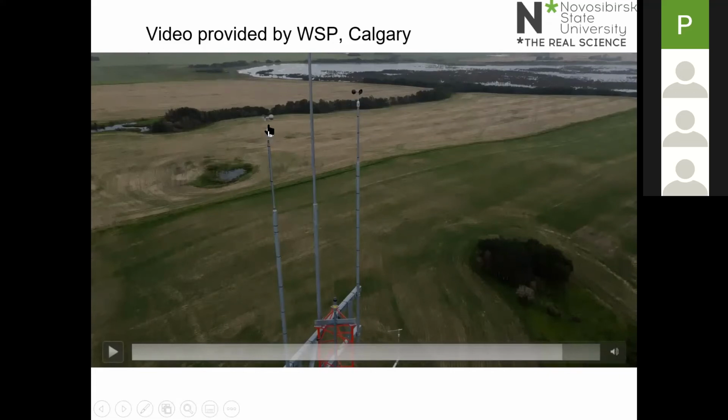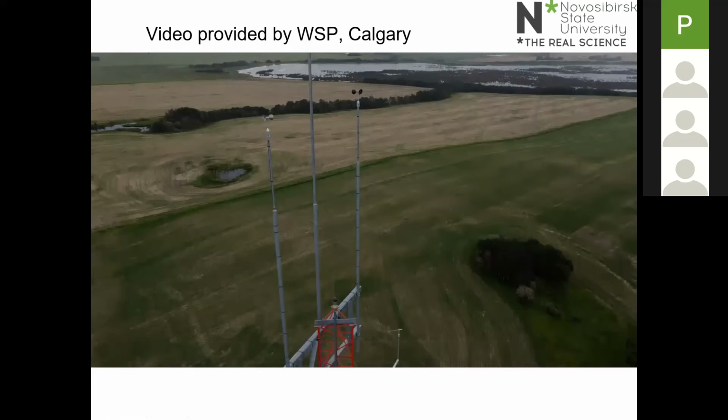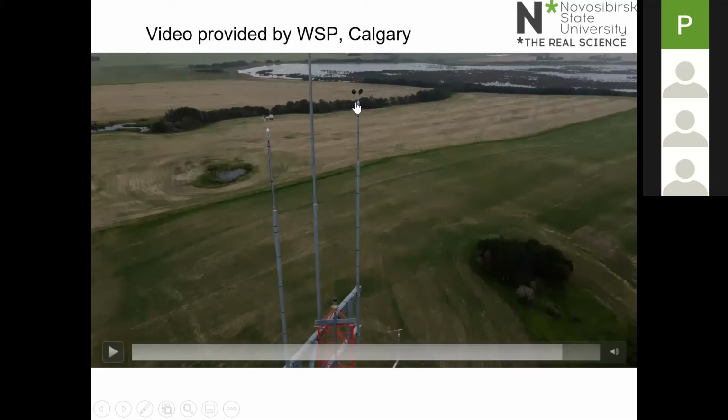And that gives extra confidence that you're getting good results. And particularly in a climate like Canada and Russia, the biggest problem that you have with these cup anemometers is icing on the anemometer in wintertime. If there's enough icing that occurs, the anemometer will actually seize. It won't be able to turn.